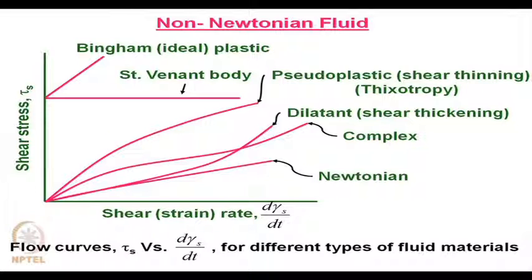But on application of pulsating load, what happens? Those water envelope layers break and water molecules get released from the sand particle, water comes out and the sand appears to be a little fluidy, some water comes out, it appears to be fluid.